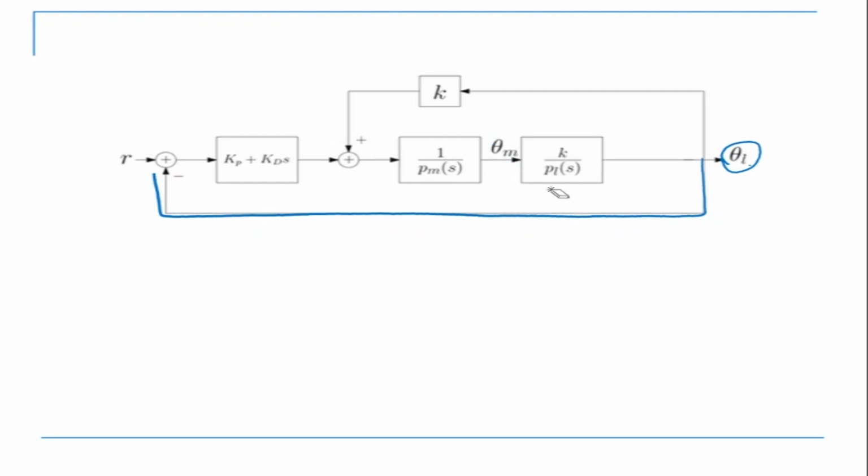Now in this case, again, we need to look at the stability. How do we do that? I have to close this loop diagram. So I multiply this into this. Then this is my G(s), that's H(s). So I multiply G(s), H(s), and then multiply with this one.